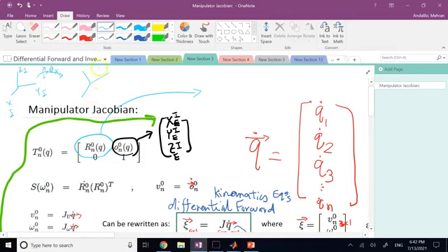Then I'm not going to rotate this new frame about the current y. I'm going to rotate it about the old y, the absolute y. So everything here has to rotate about the absolute y by an angle of theta y. So this is the rotation about y of I by theta y.